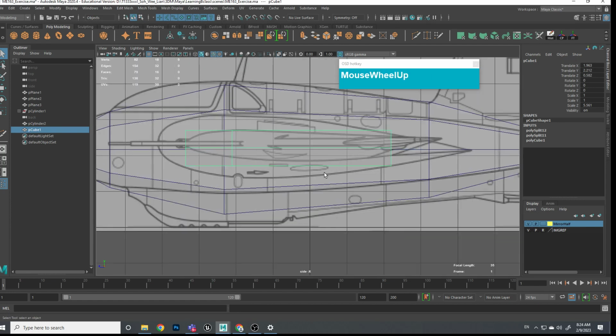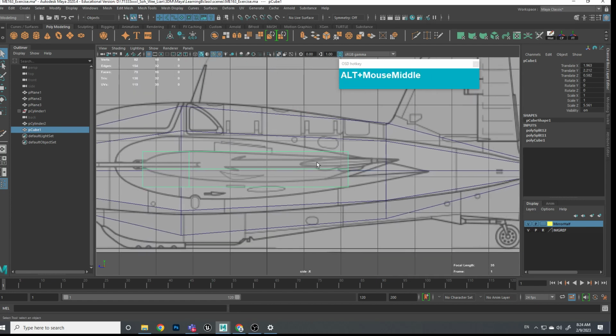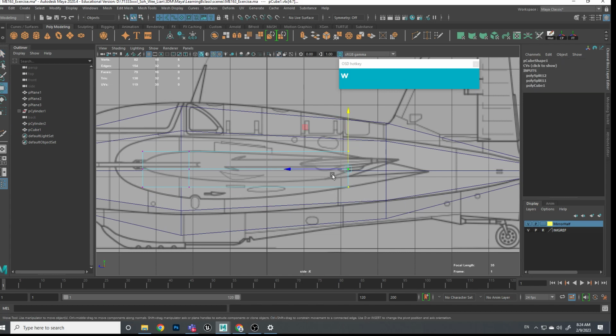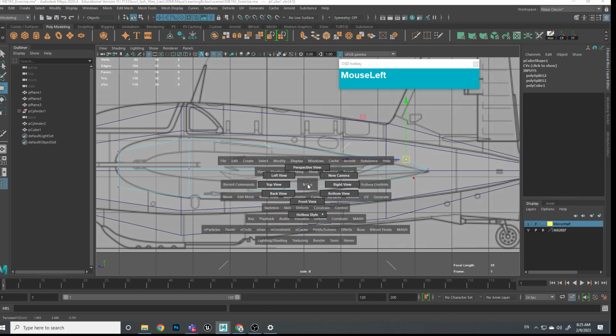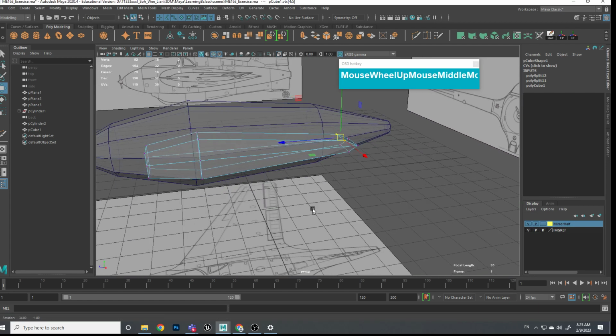Okay, so how do you reshape the wing? So go to edit mode. Grab these vertices. Press W and bring it all the way to the back where the wing is starting to appear. Then the beginning of the wing, you just bring these vertices all the way here. Then grab this vertex here, push it up. Remember, you want to create an airfoil shape for the wing. So I'm going to grab these vertices and then bring it down here. So we create the very basic shape of the wing already.